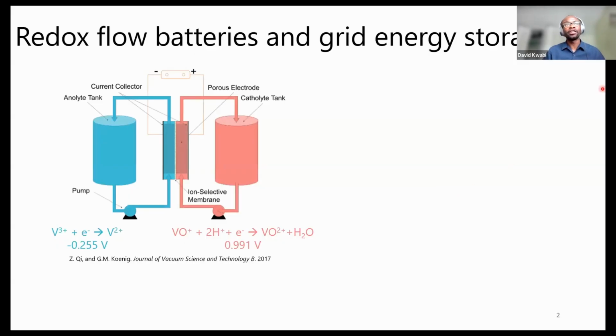And there's a schematic here of a flow battery to help me do that. What's unique about flow batteries is that they store charge not in solid materials, as we've seen already in the last 3 talks, but in redox active molecules that are dissolved in liquid form. So the way that these batteries work is that you typically have 2 tanks that have your redox active molecules or species, one called a negative electrolyte, the other the positive electrolyte. And you essentially store or release electricity by pumping these electrolytes into an electrochemical cell where you have redox reactions that help you deliver or store electricity.